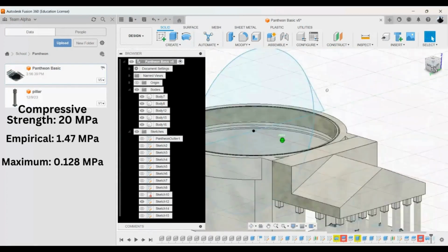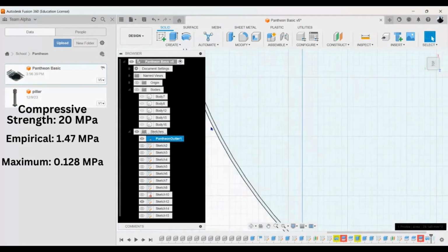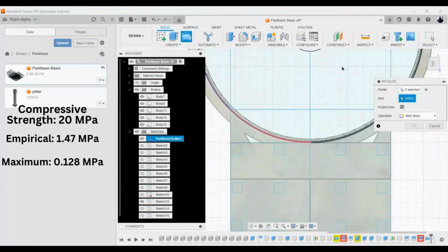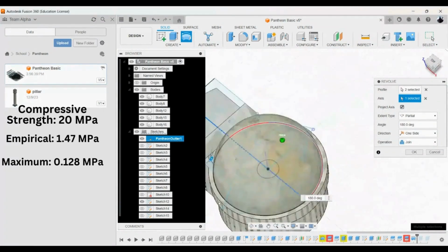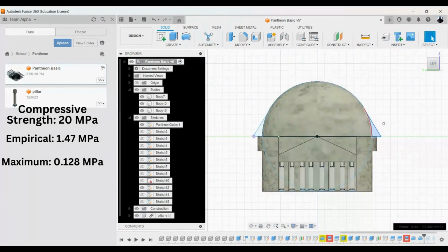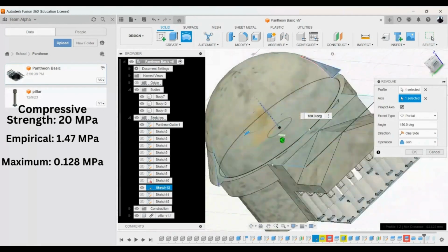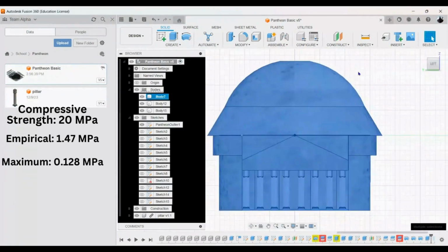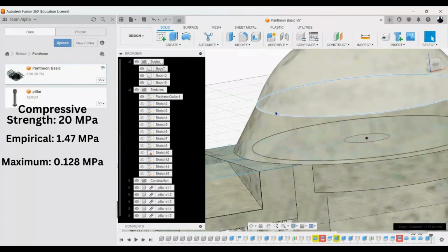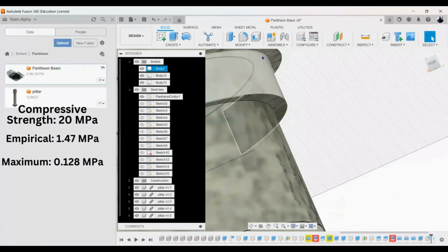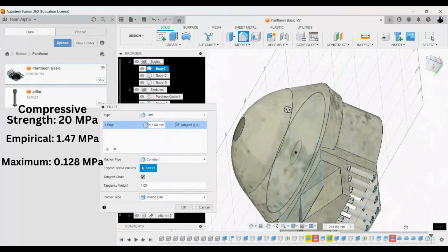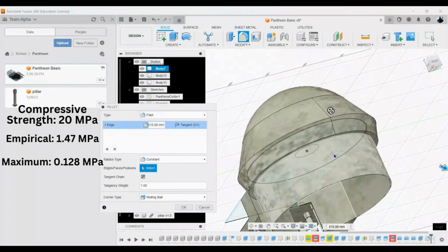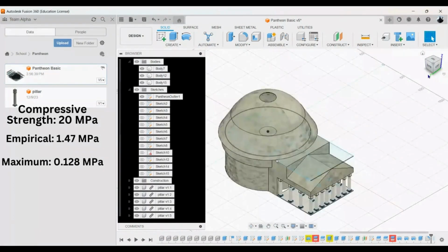Ingeniously engineered hidden chambers within the rotunda, coupled with the elimination of the apex by the oculus, contribute to a sophisticated structural system, reducing the roof's weight. The rotunda wall's upper section features exterior brick relieving arches. Part of numerous architectural devices that enhance the Pantheon's structural integrity, they are cleverly concealed by marble facing on the interior and potentially by stone revetment or stucco on the exterior.